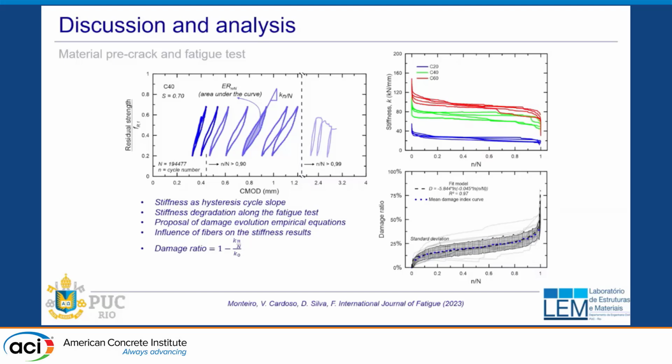So you can check it for the design, or see if the value is low, or if there is a sudden change. For example, you load it for this many cycles, and then all of a sudden you change the rate. You would do some kind of hybrid loading where you first load it to a certain level of stress, and then all of a sudden you have an overload, 5 cycles of overload to, let's say, 150% of this upper limit that you emphasize. So the stiffness can be used to see whether we can jump from one curve to the other curves.